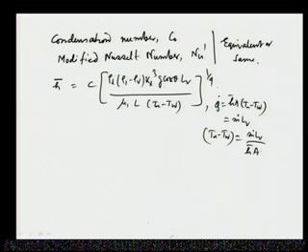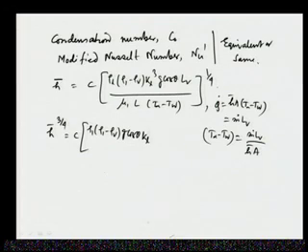This is the surface area for heat transfer. So, under that situation, if we put it over here, then we can find that H bar to the power 3 by 4 happens to be C into rho L minus rho V into g cos theta, then K L thermal conductivity cube into A by L, this becoming the geometrical parameters, mu L into m dot.